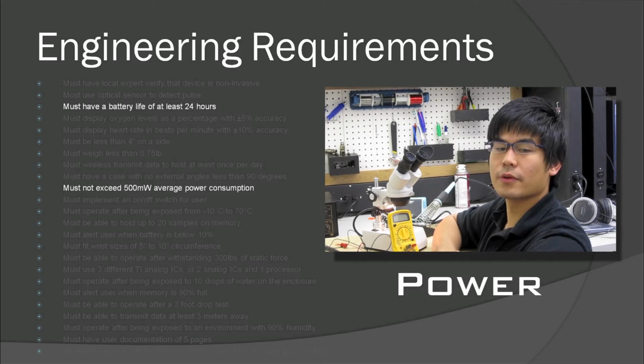Assuming that the system will sample for 30 seconds every 15 minutes, the system will be active 48 minutes or 0.8 hours in one 24-hour period. With 0.8 hours a day, 86 milliamp peak current, and a 600 microamp idle current, the minimum required battery is 69 milliamp hours. This theoretical calculation satisfies the two requirements because a battery greater than 69 milliamp hours will let the system last at least 24 hours, and the max current of 86 milliamps is multiplied by the 3.7 volt lithium-ion battery for power. The result is 316 milliwatts, which is less than the 500 milliwatt average power consumption.